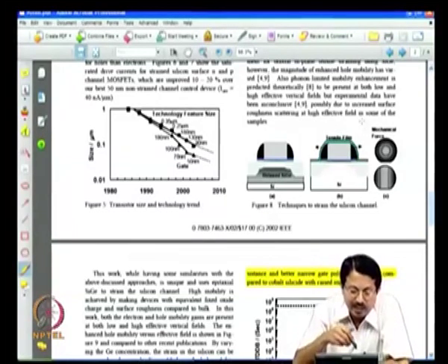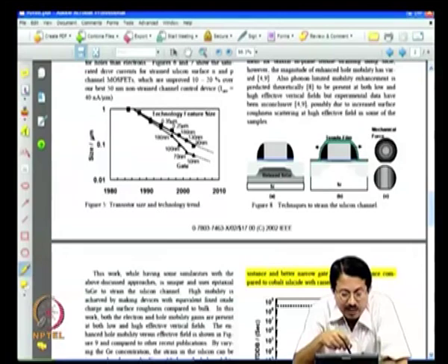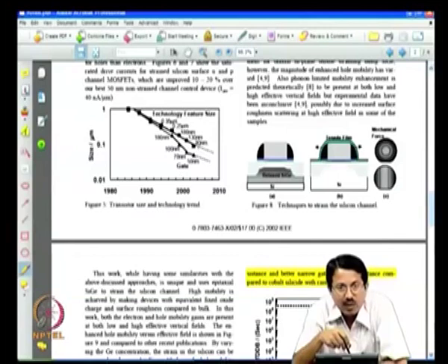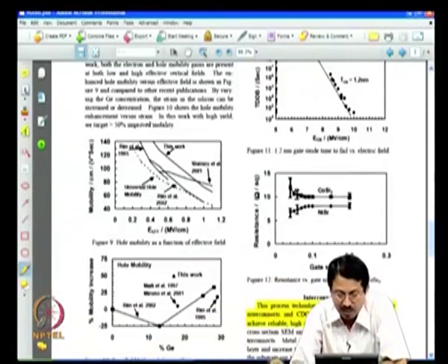They are just showing here as a function of year different technology nodes. We already looked at 180 nanometer technology, 130 nanometer. In 180 nanometer you had 100 nanometer, 130 nanometer, 70 nanometer gate length, 90 nanometer, 50 nanometer gate length. This is what I said. Now, we have a departure in terms of what gate length you print is actually smaller than the so called technology definition 90 nanometer, but in the past they were exactly identical. We have had a discussion on this in one of the earlier lectures.